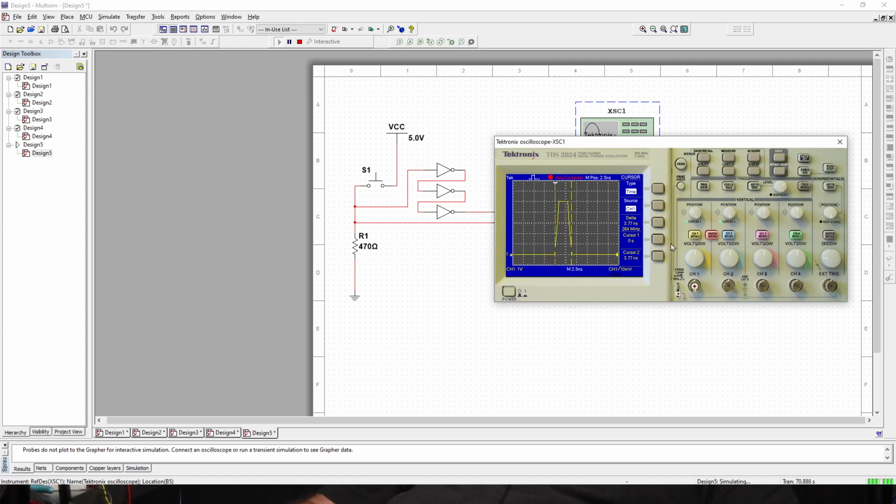But we can also check how long this pulse stays completely high, right? We're looking for 90%, but here we can just approximate that. So we're going to bring the cursors to the points where the pulse is completely high. Somewhere here. Okay, so that is the high portion of this pulse. So what do we have?